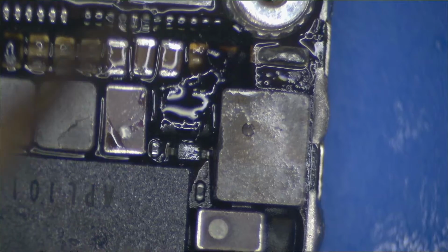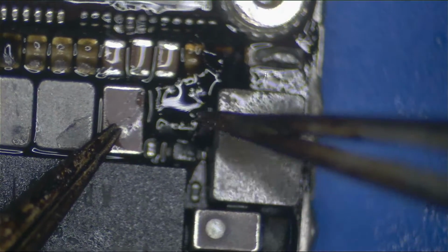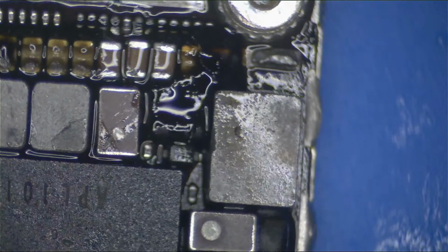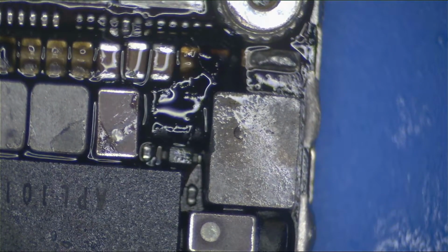But you can see the shields are removed, so I'm going to have to replace not only the coil, but a lot of the times the backlight driver too, because in the process of taking off the coil, the conformal coating around the backlight driver will heat up and cause the solder balls below it to move around, or the backlight driver just ends up being damaged. So yeah, I'm going to have to replace both the coil and the driver in this case.